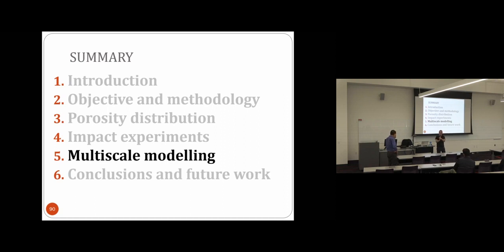So it means, in fact, having some porosity for a small fracture may not be bad. But for the ring fragmentation, which is basically uniaxial tension, and for the tube fragmentation, which is somewhere between uniaxial tension and plane strain tension, then pores are not really very good.